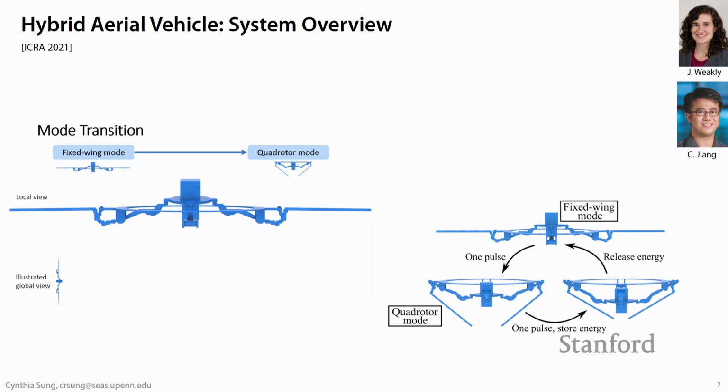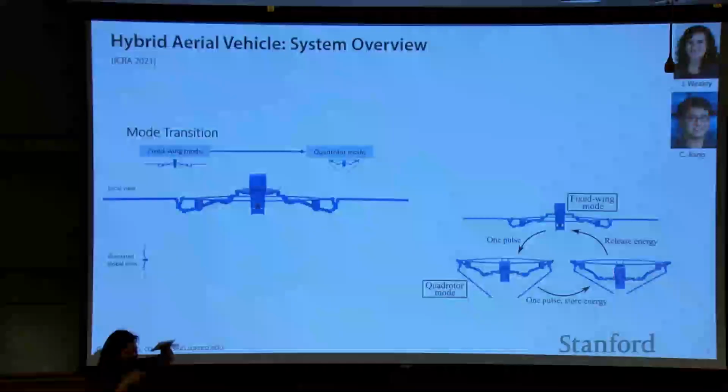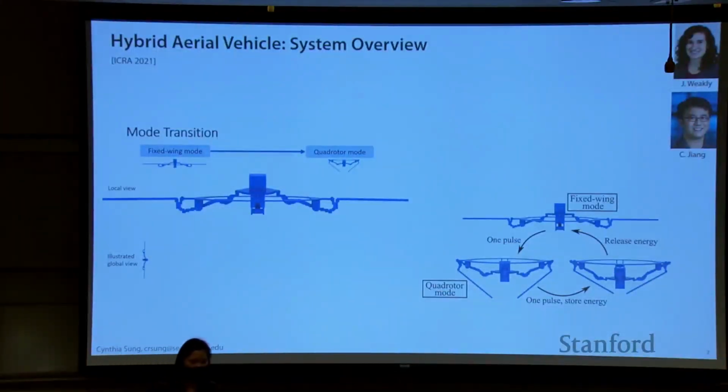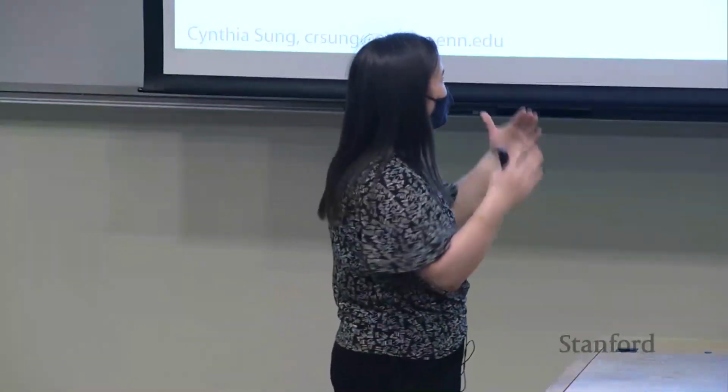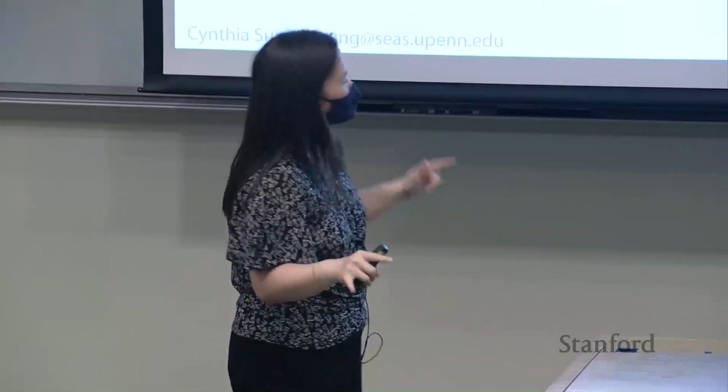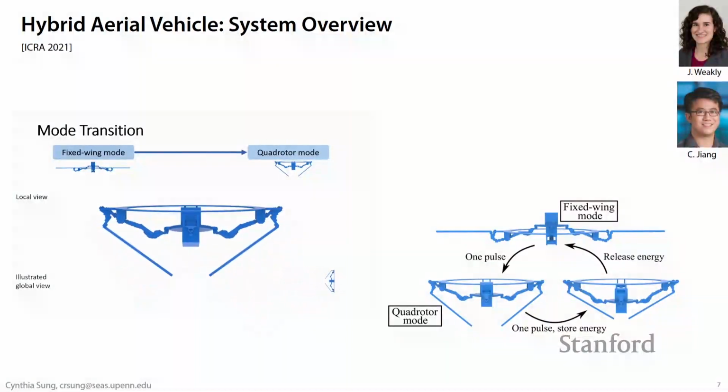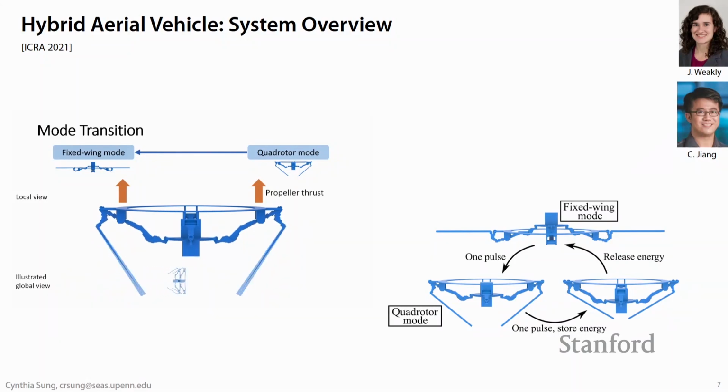So the idea here was that we would take this quadrotor, right, and we would put in compliant structures, and we would attach a wing deployment mechanism to this compliant structure so that when the vehicle accelerated, this compliant mechanism would switch, and then the wings would fold in or out, and we would be able to get this vehicle that switched modes passively by using just the actuators that are on the robot itself.